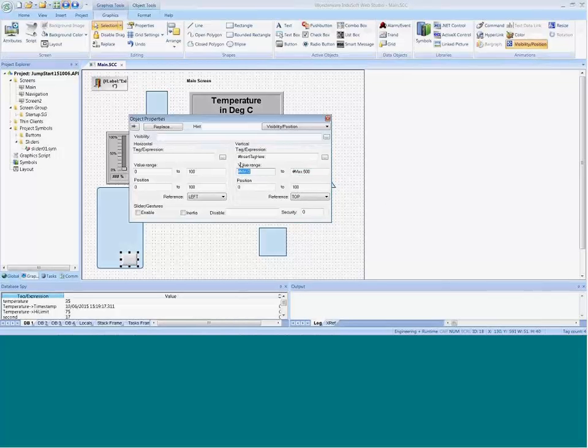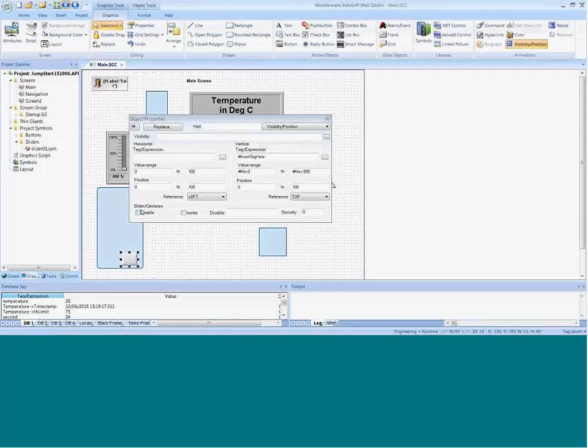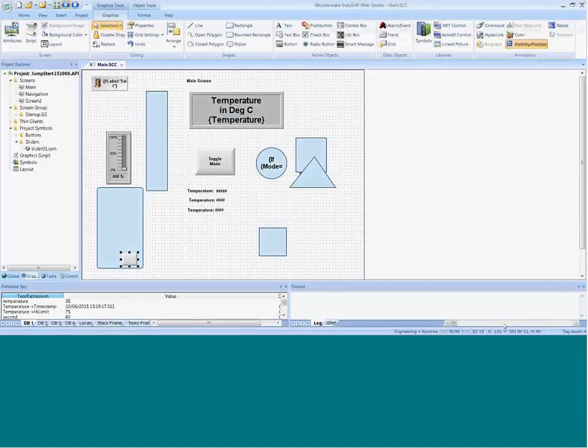So I'm going to have 3 custom properties: insert tag here with no value, minimum or min with a value of 0, and max with a value of 100. Those will be my custom properties. And then what I almost always forget is to make sure that this is set up as a slider. And I need to make sure that down here, on the status bar, my X position, my Y position is 591.